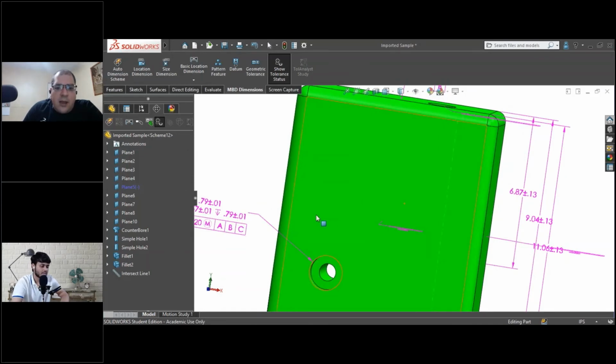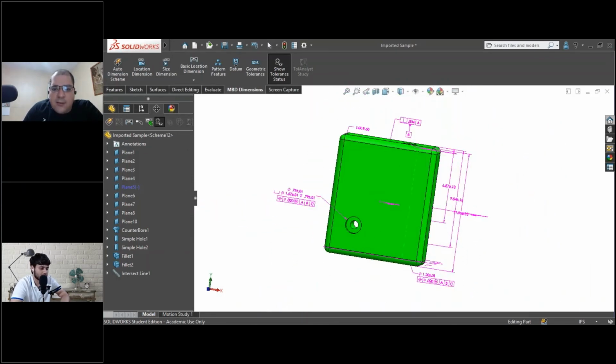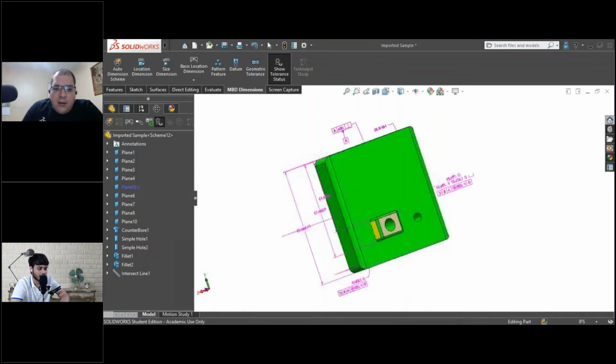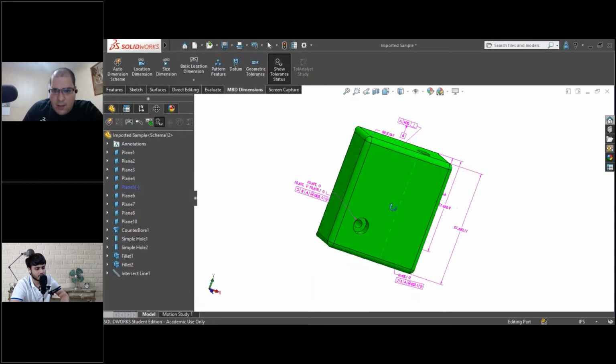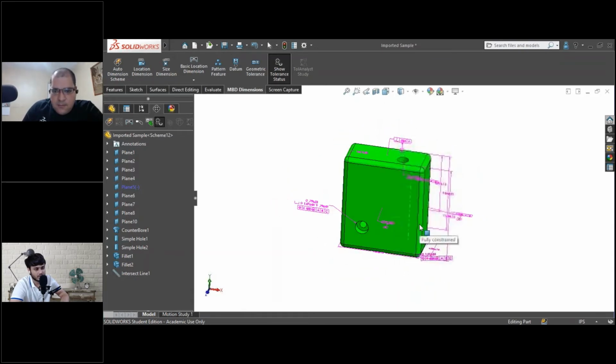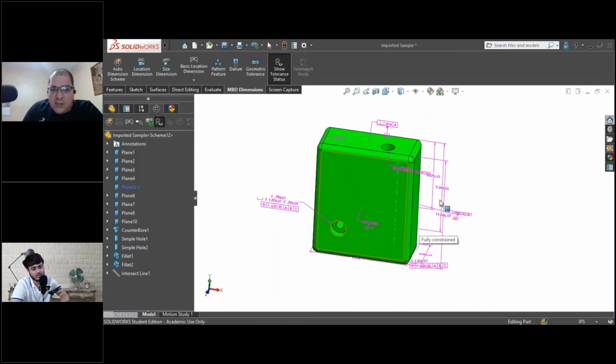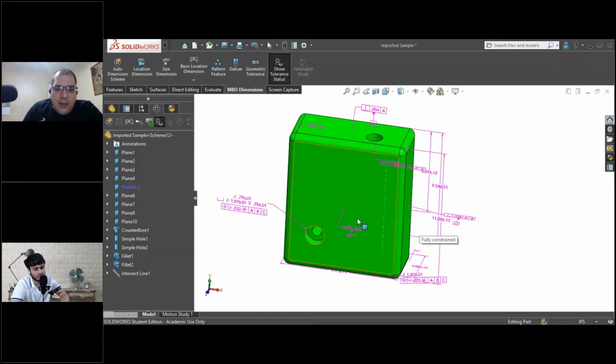So in this case, we have all the nodes needed automatically, without any previous operation or any previous nodes or dimensions for the model. It's just an important part, and SolidWorks automatically brings the dimensions here. Also, as you can note, the datum A, B, and C came automatically from the planes I selected as datums.